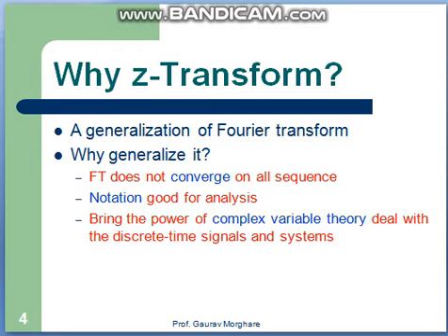And the formula for the Fourier transform is the integration from minus infinity to plus infinity of f(t), which is any signal, into e raised to the power minus j omega t. That should always be finite. So where the Fourier transform has the limitation that it does not converge for all the sequences, the Z transform can easily be calculated for all these signals.